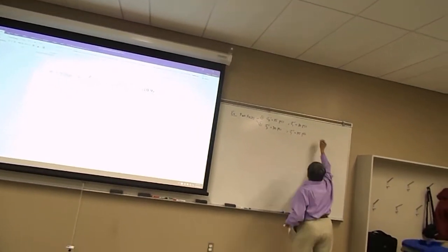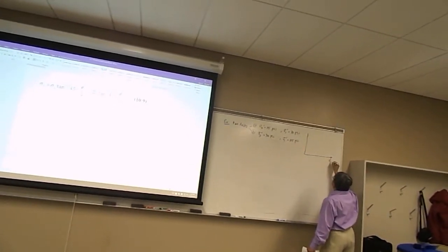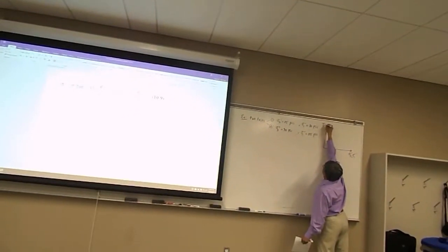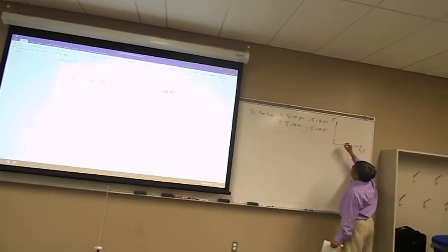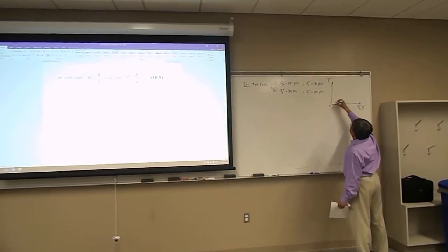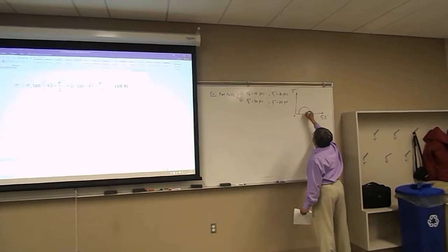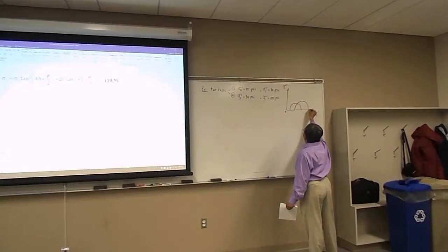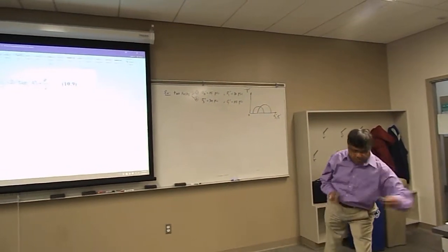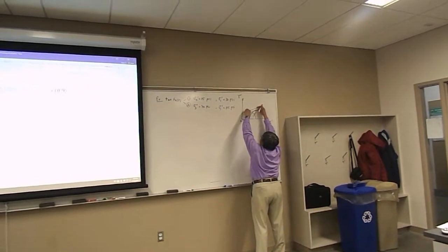So what you can do is draw sigma 3 prime, sigma 1 prime, tau prime, and 0, 15 to 70, one circle, and 30 to 115, another circle, and then take this straight edge and draw the Mohr Coulomb failure envelope like this.